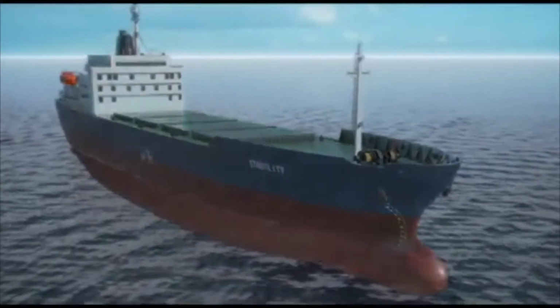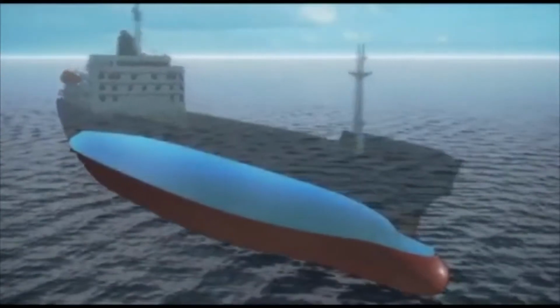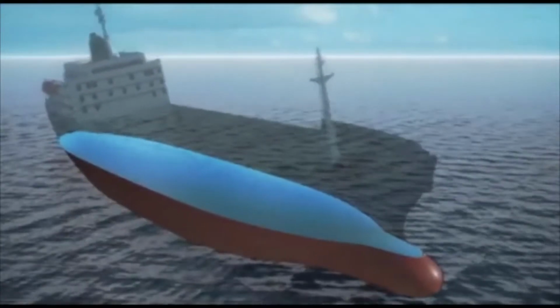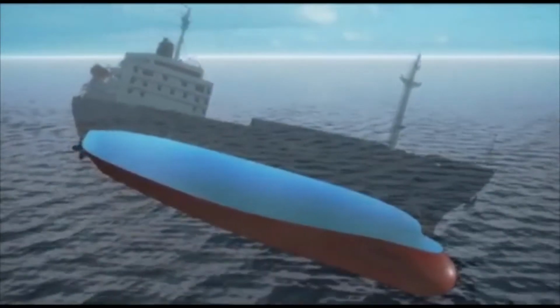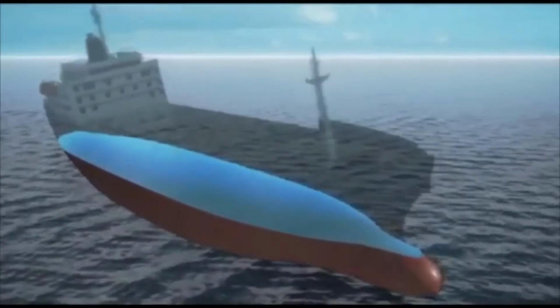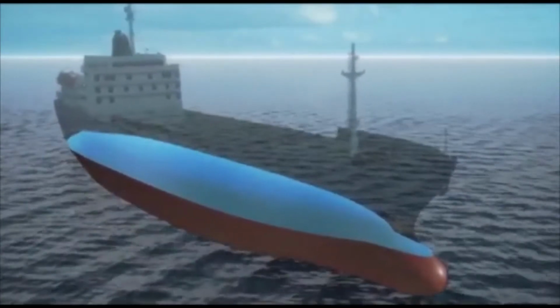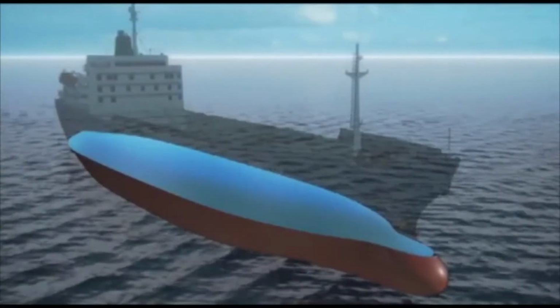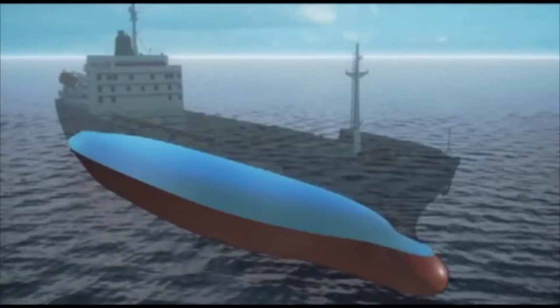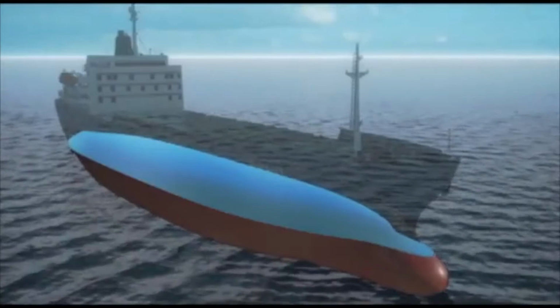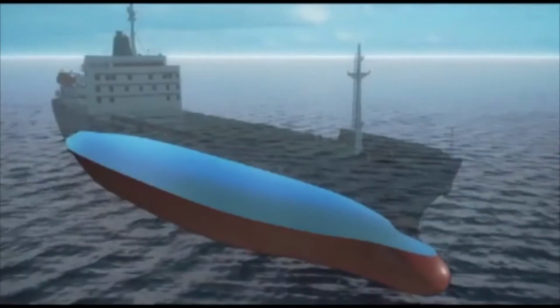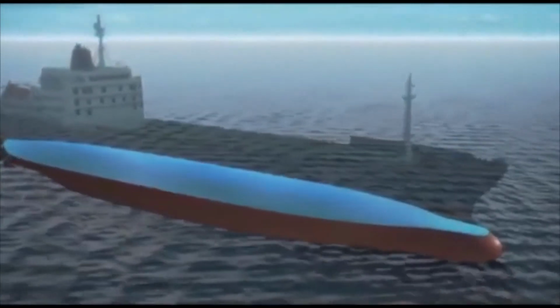As a vessel rolls in the water, its waterplane area increases as long as there is freeboard available to add to it. The larger a vessel's waterplane area becomes when it rolls, the more buoyant force it develops. This is why freeboard is indicative of a ship's reserve buoyancy, or additional buoyancy at larger angles of roll.